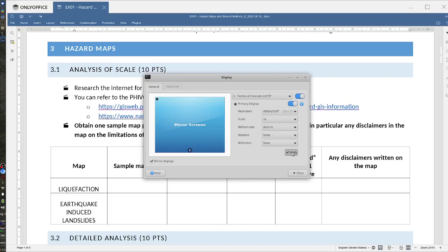Going back, you have this equation for surface rupture length. This is the magnitude, and then A and B are your constants. In here, they have a value for A and B depending on the type of the fault. For strike slip, you have this value. For reverse, you have this value. Normal, you have this value. If you don't know the type of the fault, you can just use all. So you can just use this one.